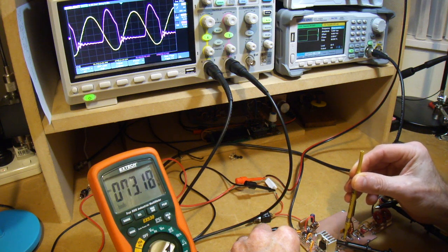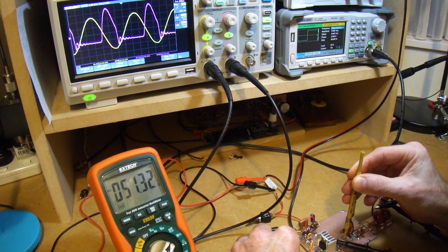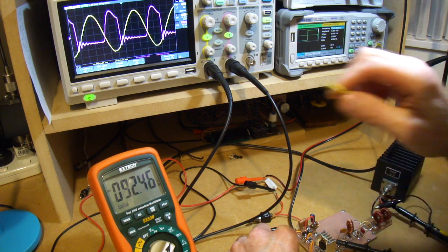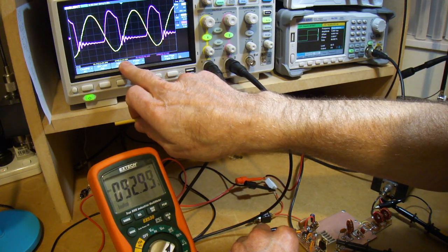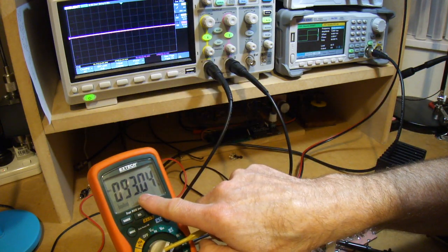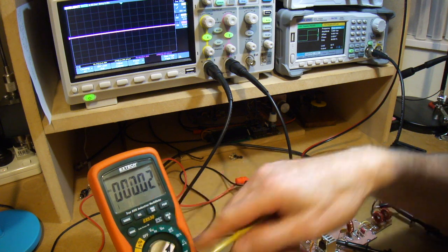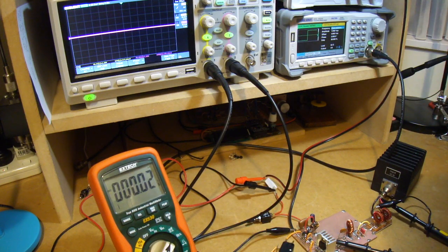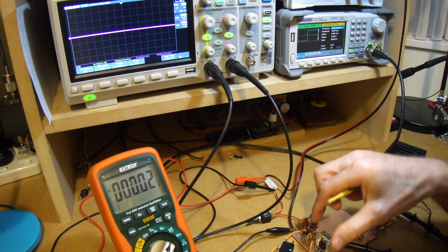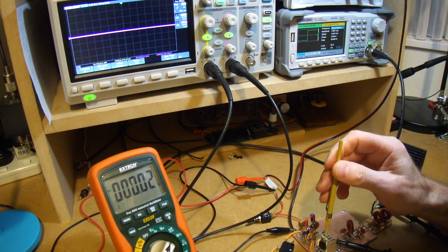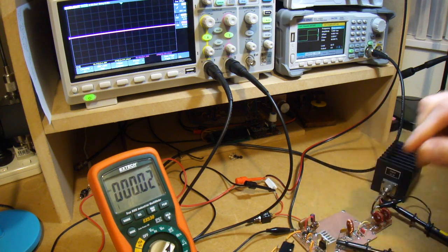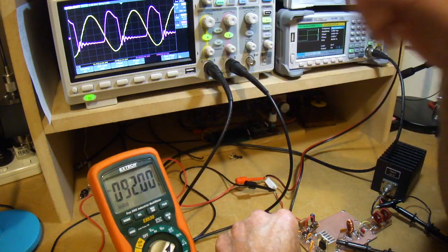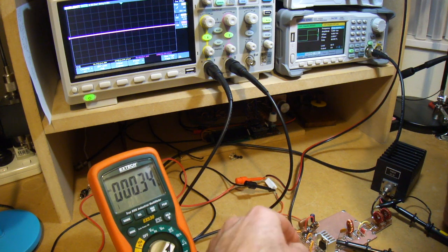So why not go for gold and eke that out to sort of 19 volts there, 19 volts RMS across that load. Sure, I'm drawing now 0.93 or 0.9 amps, but if my efficiency is the same as what I was getting at 5 watts, why not? That current is still way less than what the device can handle, which is 5 amps. The voltage across it is 50 volts, so I'm allowed up to 100 volts on that particular device.